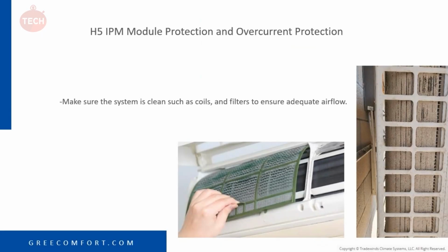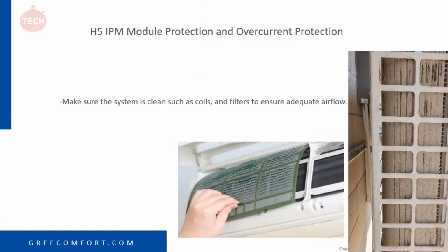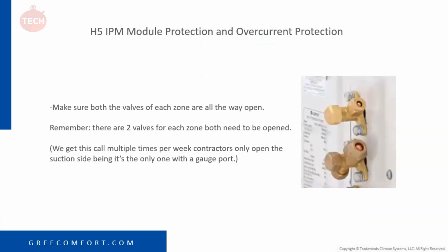Of course, make sure that the filters are clean, coils are clean. Definitely generate an E6 code. So you can see in the picture on the right, that unit is caked. Clean that up. It could be what's causing your issue. Zoom in on those.